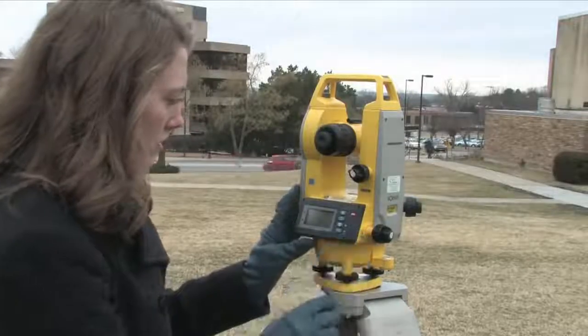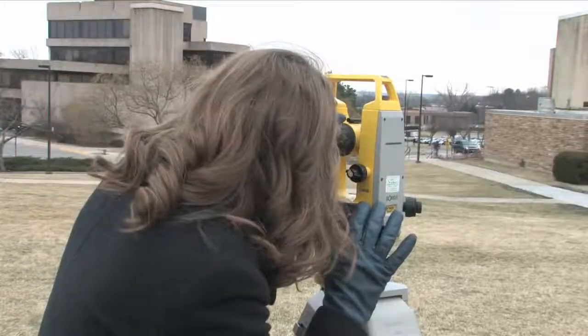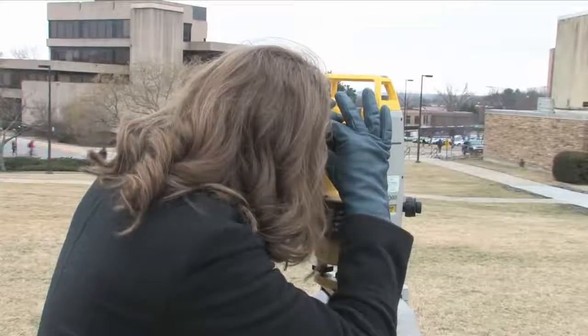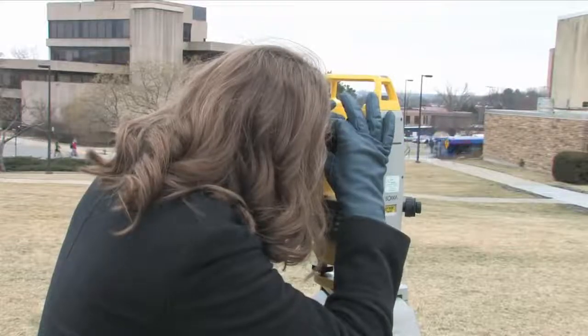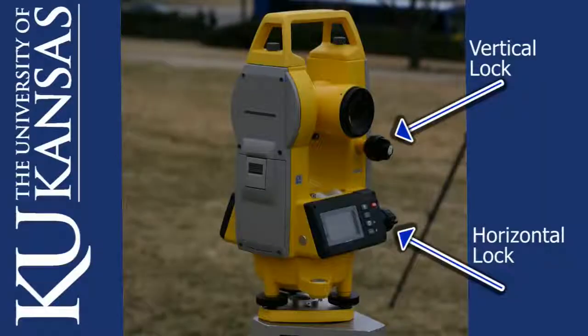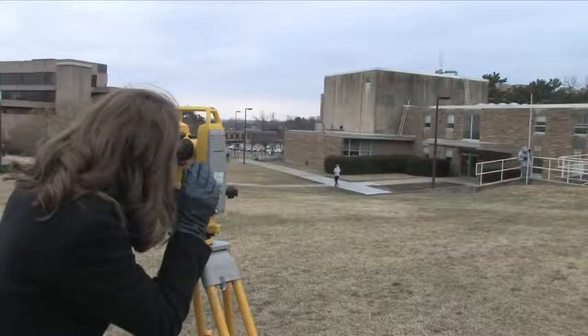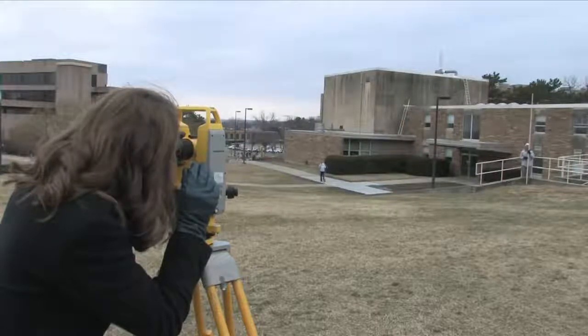To begin, the instrument operator removes the lens cap if they have not done so already and presses the red on button to activate the digital theodolite. Then the instrument operator sights the scope on a rod at point A, focusing specifically on the HI. Once the scope is very nearly sighted on the HI at the rod at point A, the instrument operator will then rotate the horizontal and vertical angle locking dials on the instrument to hold the angle. Fine adjustments may be made by rotating the dials immediately behind the locking knobs.